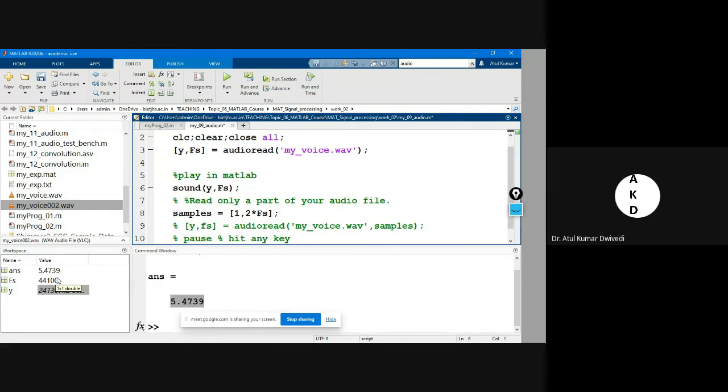No, this is the sampling frequency. This is not the maximum signal frequency. Audio frequency cannot be such high. I am saying that sampling frequency is nothing but the Nyquist rate. We have to consider the Nyquist rate. Voice signal is 4 kilohertz for a human being. That into 2 will be 8,000 samples for our voice information.